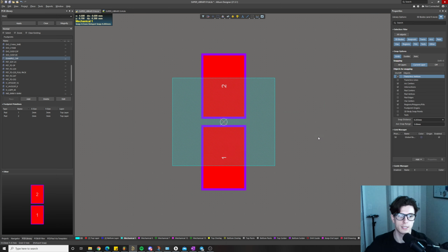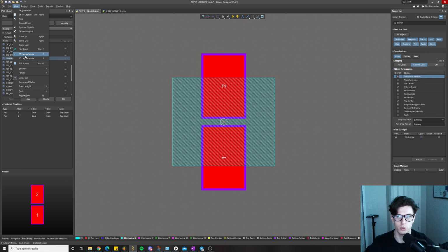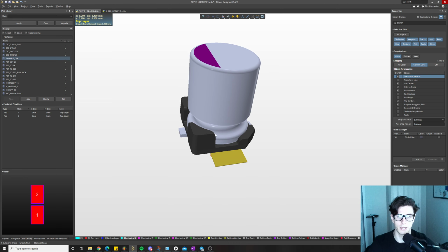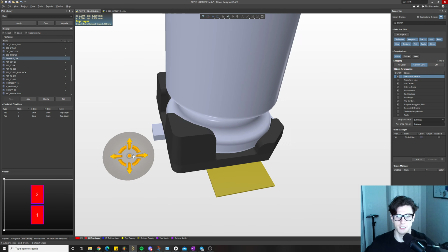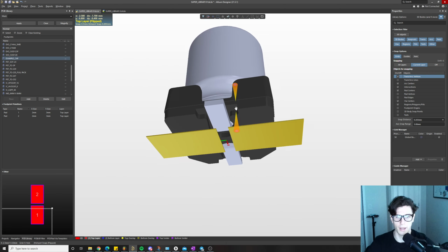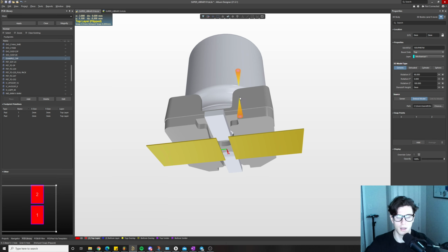So one important step we need to follow before we go any further is there's like a default orientation for these components, and sometimes it doesn't always line up with how you laid out your pad. So real quick, you want to go to the view 3D layout mode and make sure you see, okay, so this doesn't make any sense because it's the wrong way. It needs to be rotated like 90 degrees in the, I'm not sure which, we're just going to do trial and error to figure out. I do not know these.